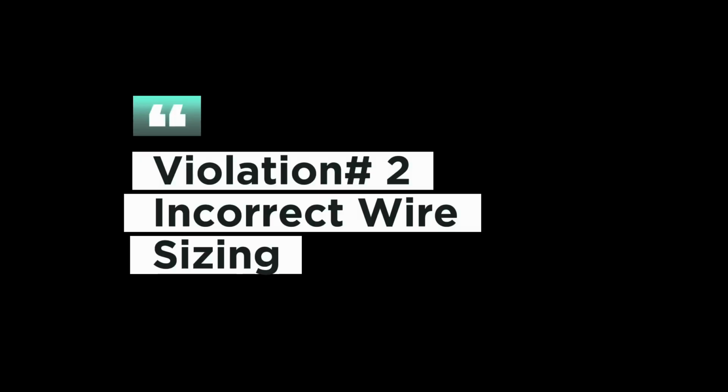Violation number 2 that I see very often is incorrect wire sizing. To choose a wire size, each wire size corresponds to an ampacity. Ampacity is the maximum current, measured in amperes, that a conductor can carry continuously without exceeding its temperature rating.